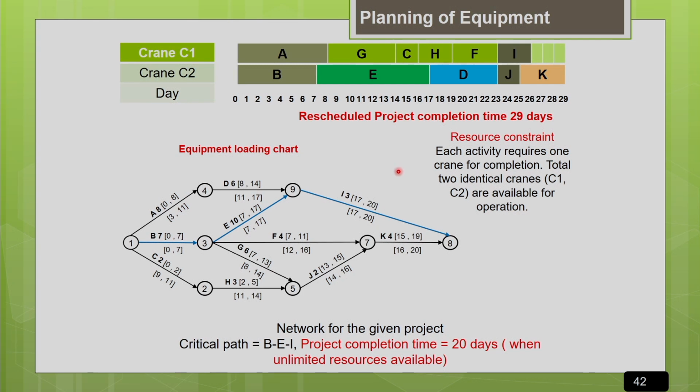So how to allocate the resources? On what criteria are we going to allocate them? We will go by the simple approach commonly followed in many construction project sites, the least total float approach. We are trying to identify the activities which are more critical. Whichever activities have the least total float are more critical. As I told you, the activities which have 0 float are called critical, and the activities which have less float are close to critical.